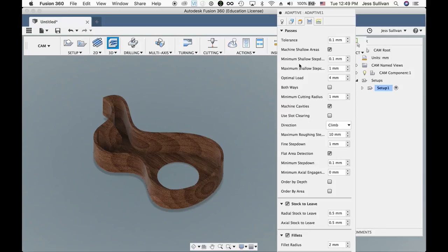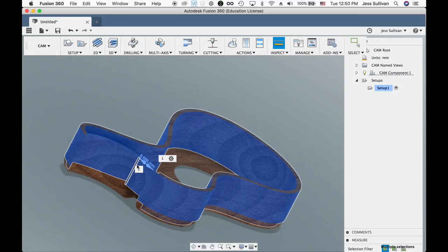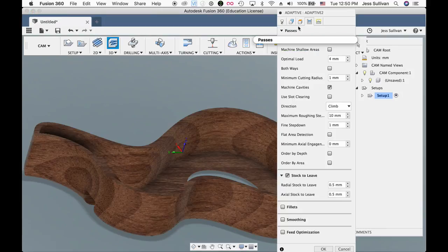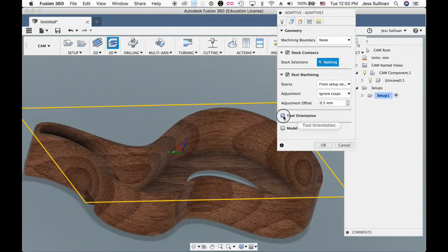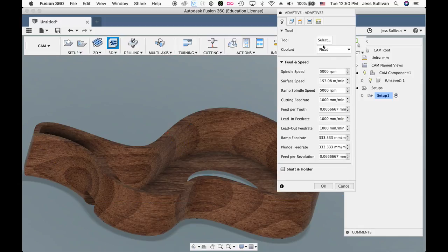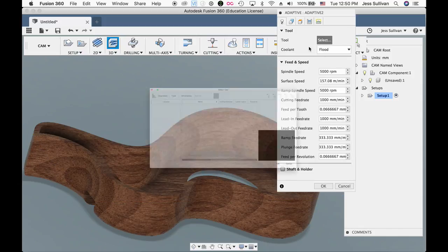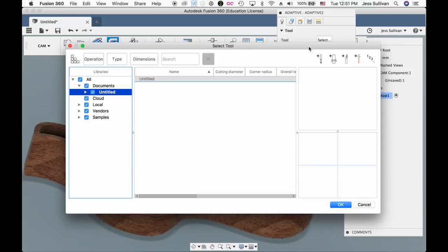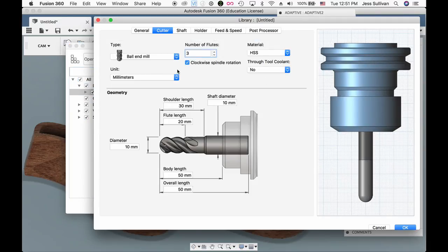Before moving to the tool pane, select a vertical edge on your model. If this length is greater than that of the router bit, you can imagine what will happen. The router itself will collide with the tallest section of your model. To avoid this temporarily, and learn about the tool window in doing so, we will make the router bit longer than the largest vertical distance.